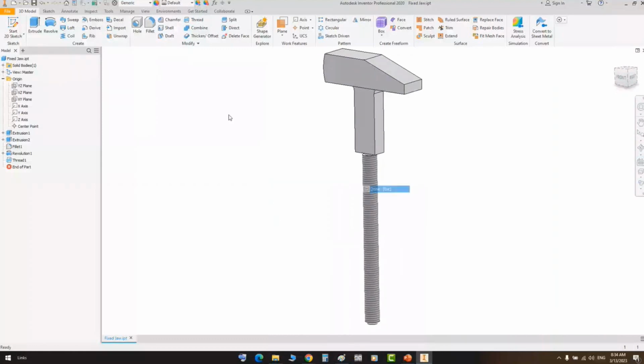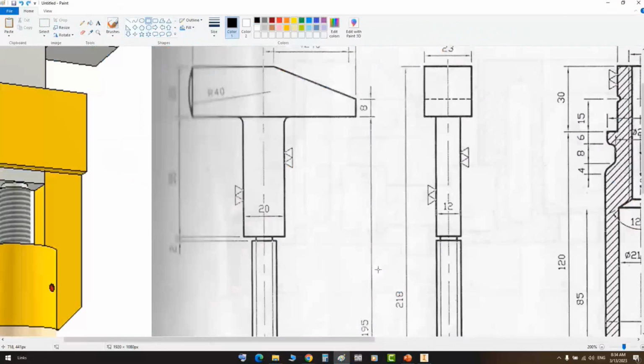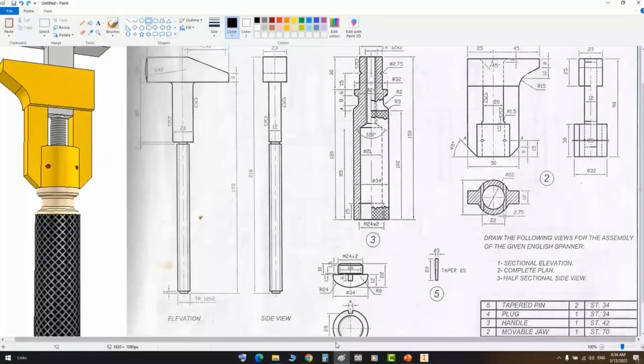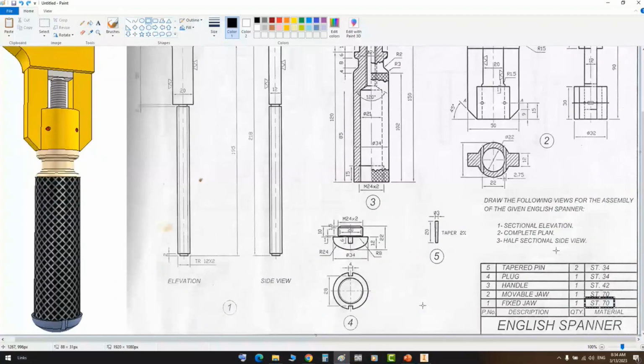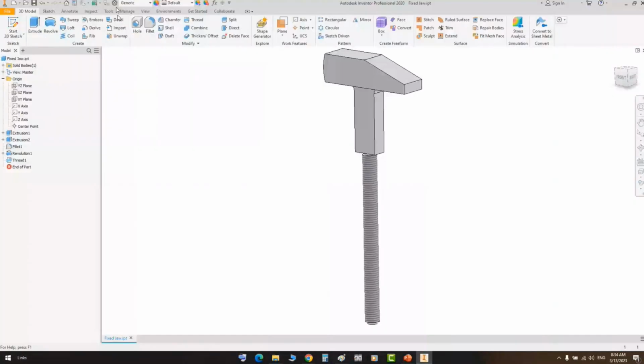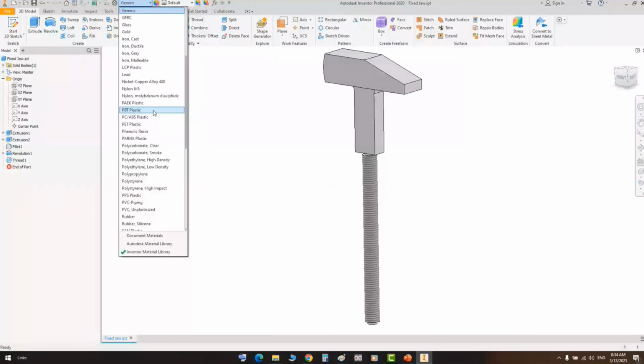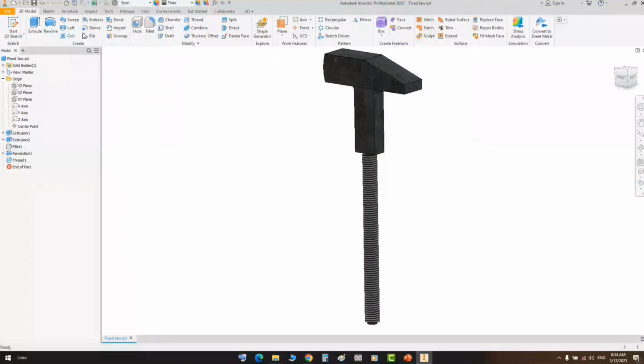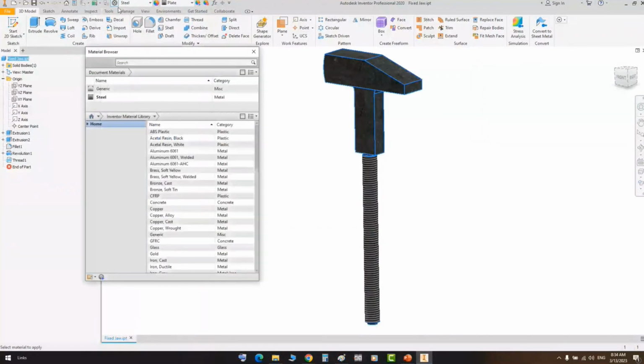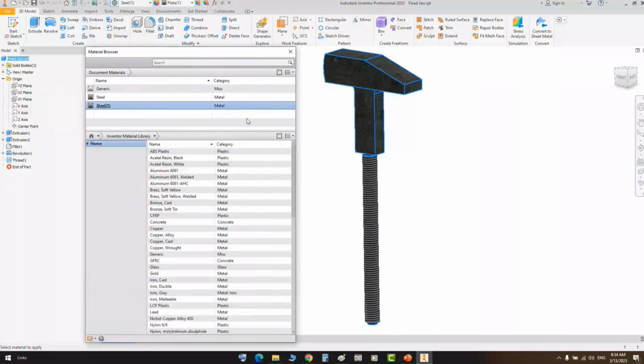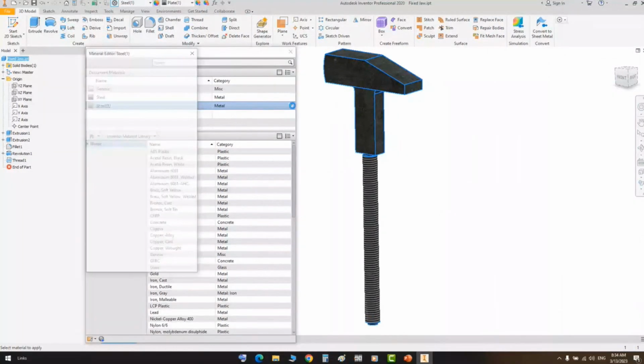From here, if we take a look at this drawing, you can figure that the material of this one is steel 70. So to define a material like that, we will select a near material for that, which is steel, which has the same density and near mechanical properties. After selecting it, you can open the editor of the material, and from here you can make an edit from this one, or you can duplicate it and keep the original material here. Select steel one, which is a copy from this material, and you will find the list here. After that, you can make an edit for this material.